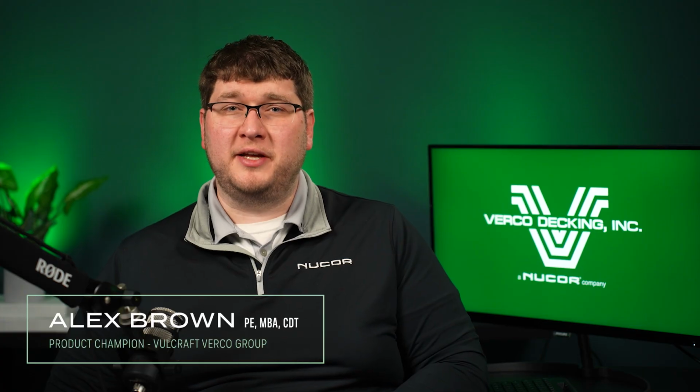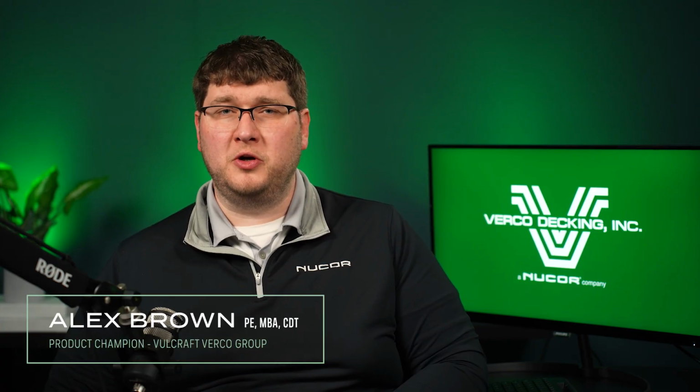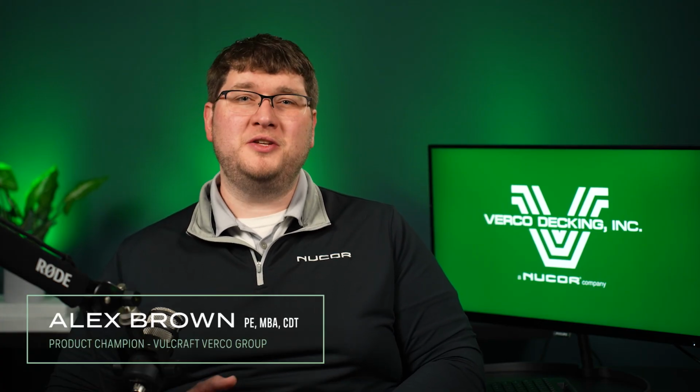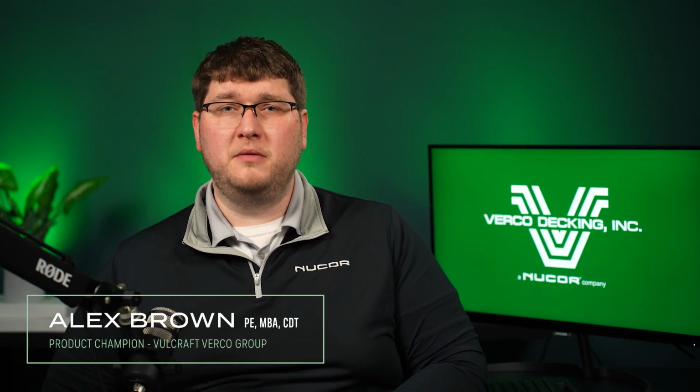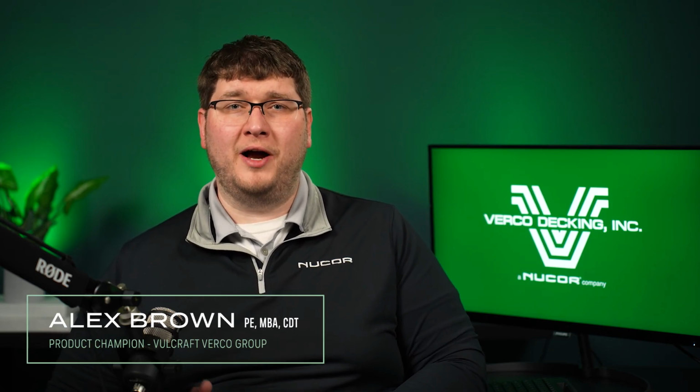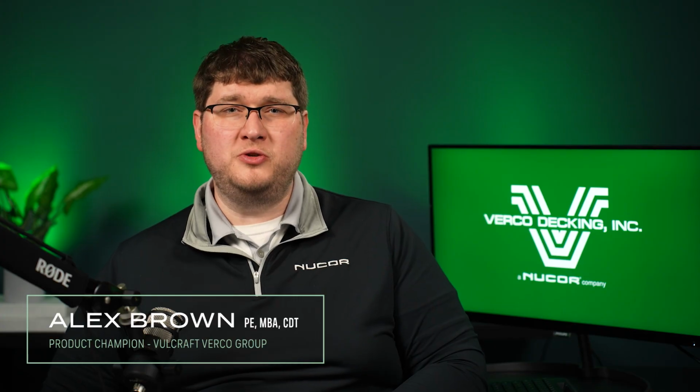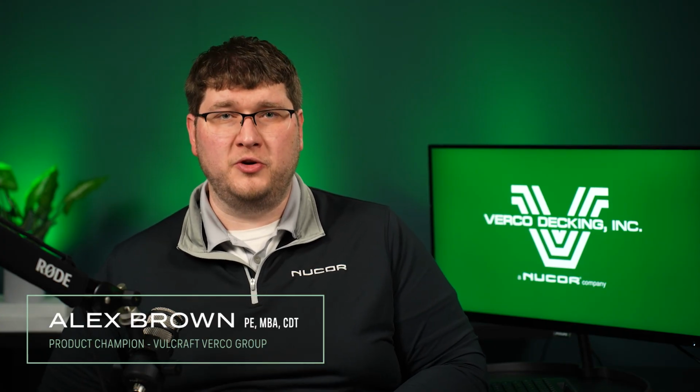I'm Alex Brown, and I'd like to introduce you to the UL Design Lookup aid for floor systems. This tool allows you to quickly filter through UL fire resistance assemblies based on hourly rating, deck profile, and protection methods, which allows you to quickly select an appropriate assembly for your project.